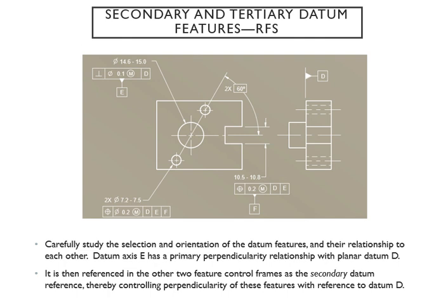So anyway, we go into this, of course, this is the same example. We're still studying how to select and orient the datum feature, which is here, here, here. These are little triangles where you can spot all of your datum features: your primary, secondary, tertiary, and this is your single datum feature. Two of them, primary and secondary, here.